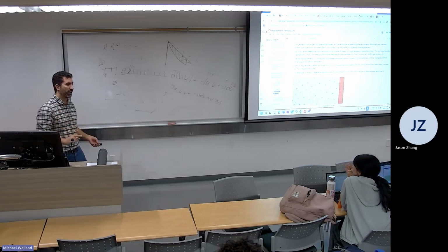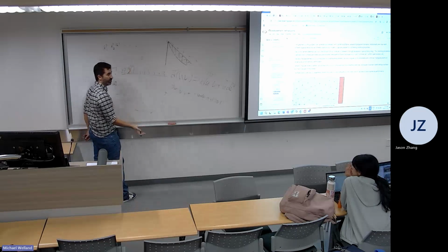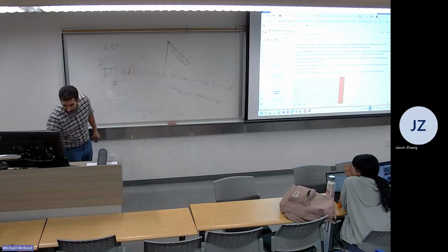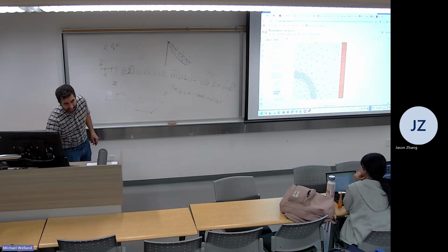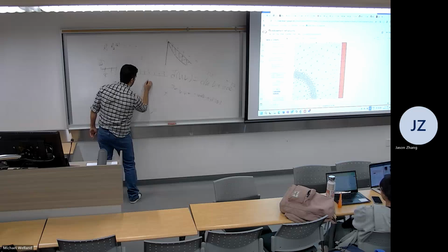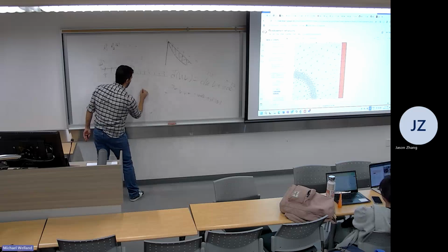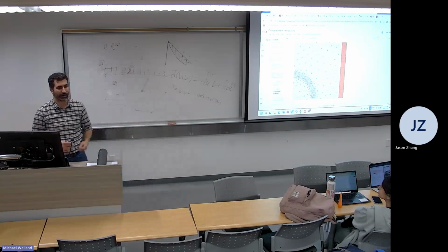You do have to be wary of something called element quality. That's COMSOL's term. Basically, what you're saying is that one of these edges doesn't go to 0, right? Even here, like where you have these three, four, five that are all connecting to a single point, this triangle is getting super narrow, right? At some point, this is going to turn into a line, and once you're a line, then you have degeneracy in your element.